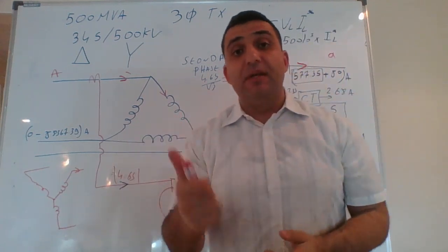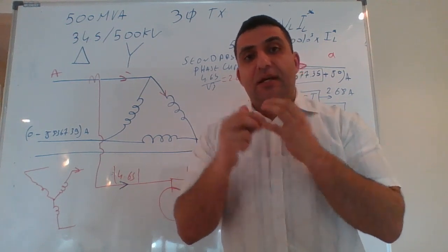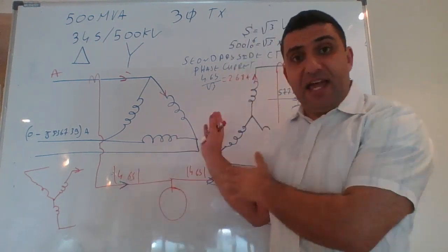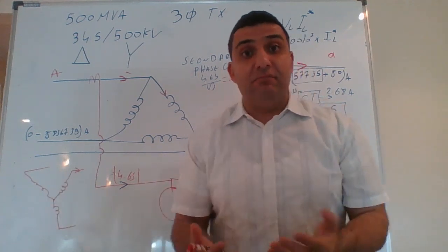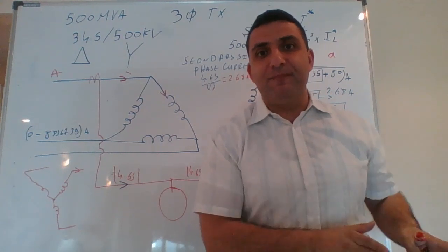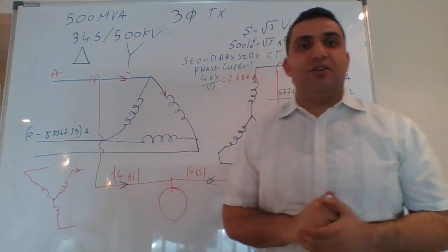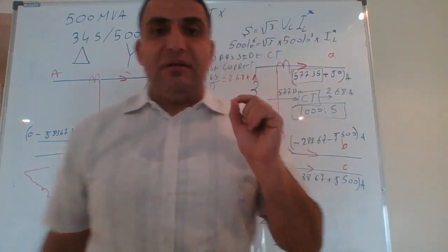That's one element. The second element is the underload tap changer. Does it have one, yes or no? I will eliminate it. Then I will have CT error. The type of CT that I used, of course, has an error. We already did it before. And the last one is your margin. I hope that's clear.